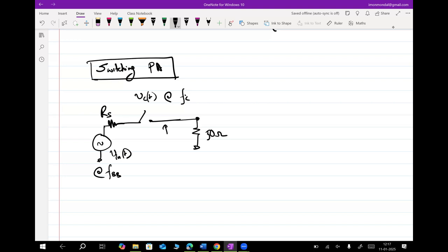With respect to the load and so on, right? So fine, but for the same source resistance, you can say that one signal has higher amplitude, one has low, which means the one is a stronger signal than the other. Unless you specify source resistance, it is very difficult to justify whether one signal is higher strength or lower strength, right? But in wireless, it is often assumed that everything is 50 ohm. So the moment we say it's a stronger signal, we assume that across a 50 ohm load, one delivers higher power than the other. So that's the inherent assumption.